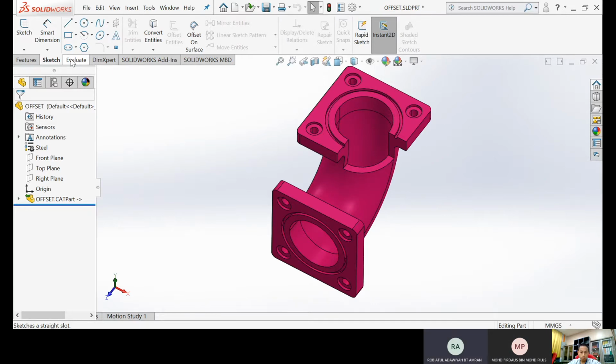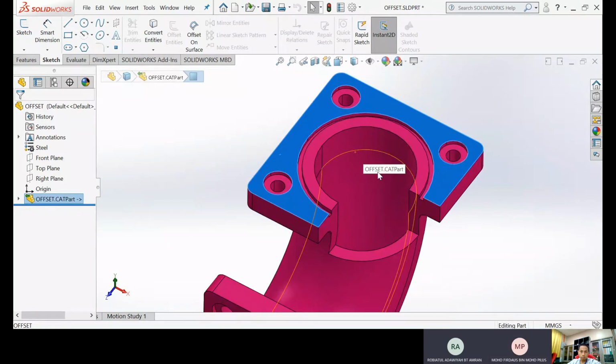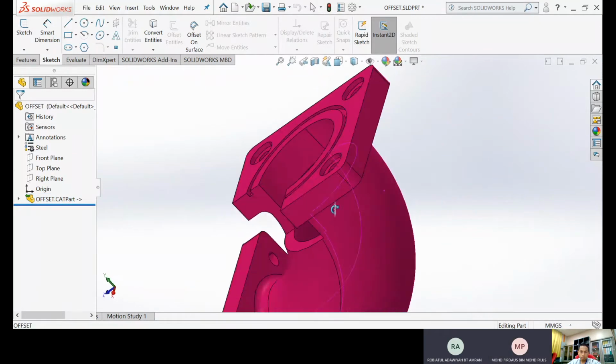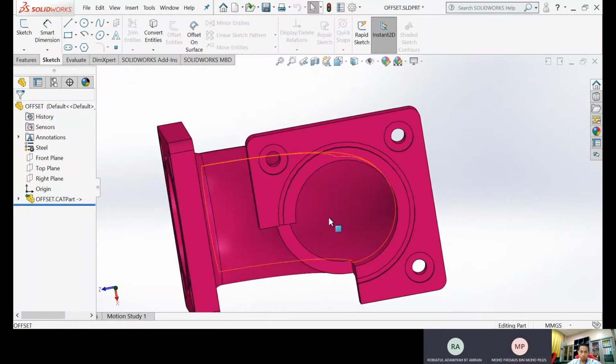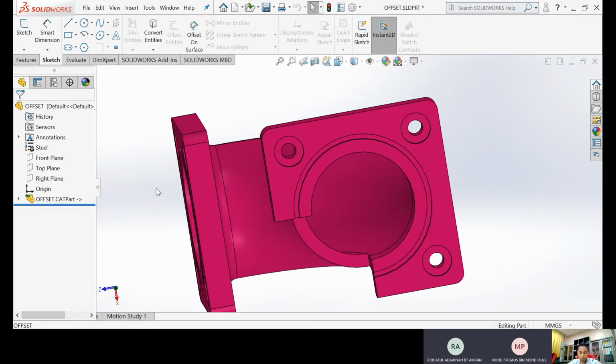First, it is very important to focus on areas selected of the scanning. Use areas selected that have a good clean scan and information that can be used to create a 3D part. Select STL edit and make sure to notice the number in the dialog box as it has an important value, because it is dealing with the number of polygon faces to create the STL. Use select reference, select the origin in any point, select X direction, Y direction, while Z direction is automatically pointing out. Noise removal is information that is floating out in space.